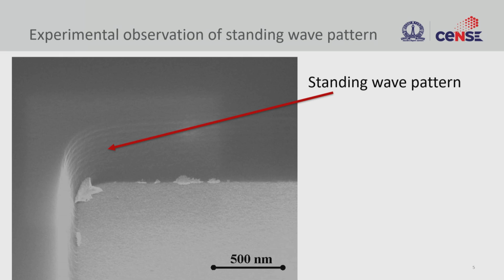This is a scanning electron microscope image of a photoresist after development, and you can see the wavy pattern here, right. So, you can look at the pattern here, which is clear that there is a standing wave created because the anti-reflective coating was not there. Okay. And if you are going to use this for dry etching, you are going to transfer the non-uniformity that you have on this photoresist onto your silicon or underlying pattern. Okay.